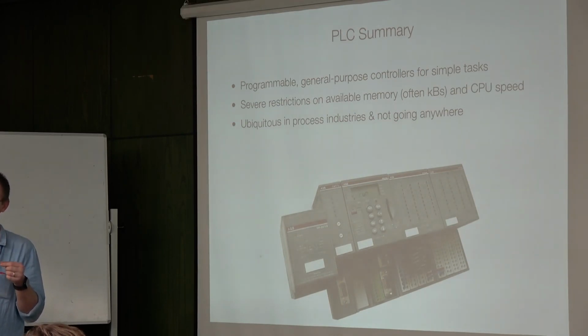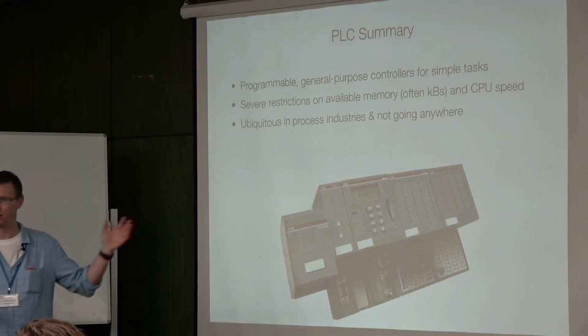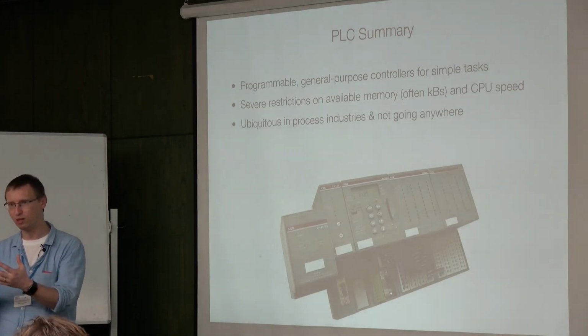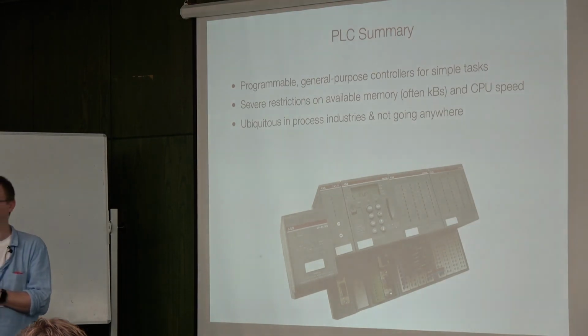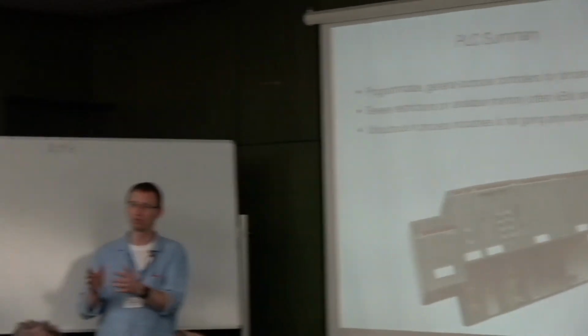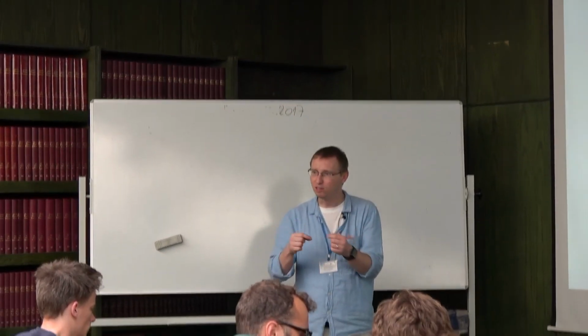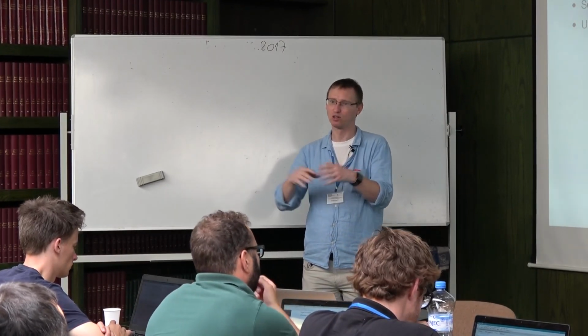Again, the devil is in the details. How does the particular programming environment store those files? For instance, the environment we will use uses an open XML description, so pretty much everybody can take those files and transform them, say, for Siemens SIMATIC PLCs. So that is possible. That's also the big strength of PLCs, that everything is standardized, and you can take literally the same program and implement it on hardware of any producer. So it's not that you would be running on some unsupported functions and so on. That's also why the language is so limited, because they have to accommodate the lowest common denominator across all platforms.